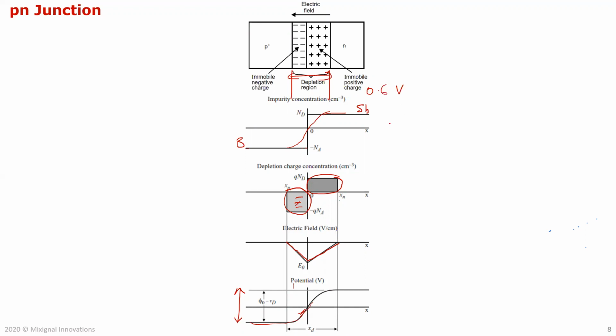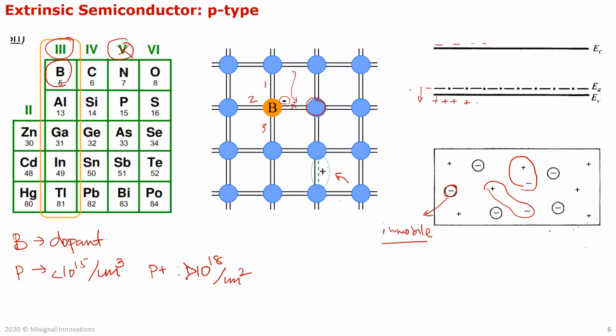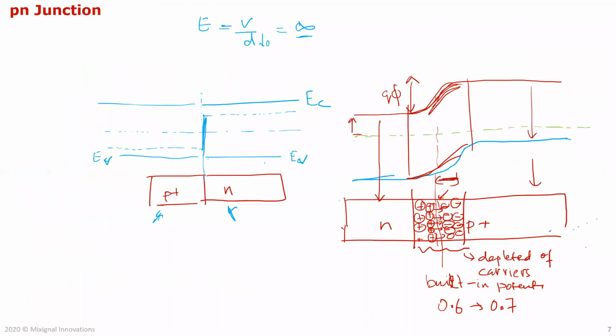Okay. Another thing I wanted to mention: if an electron jumps to the conduction band, it needs at least, in silicon, 1.1 electron volt. Now let's say you have more energy, for example 1.2 electron volt. It'll use the 1.1 electron volt to jump, and the rest of the energy is converted into kinetic energy. That's what causes all the heat and the Brownian motion. This is even before you apply any voltage to it.